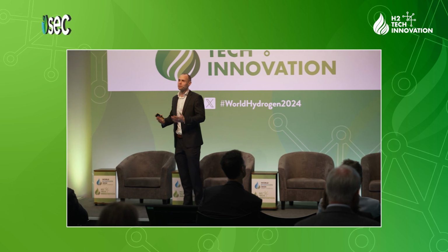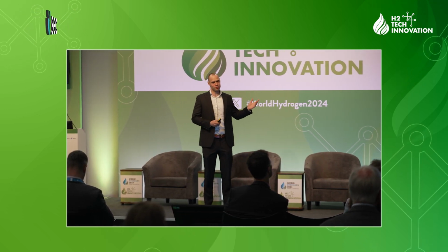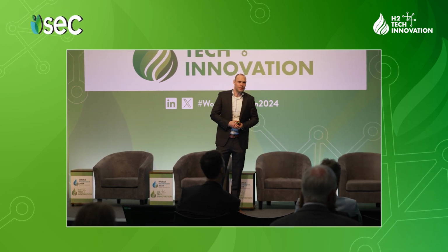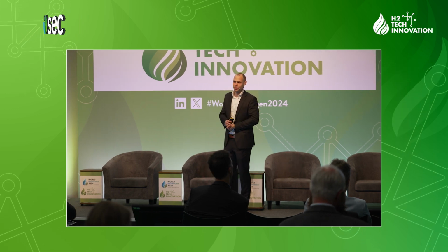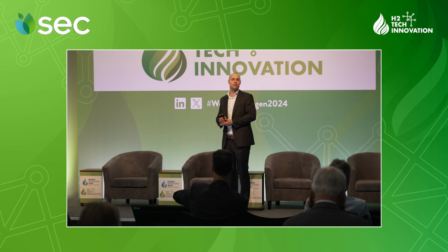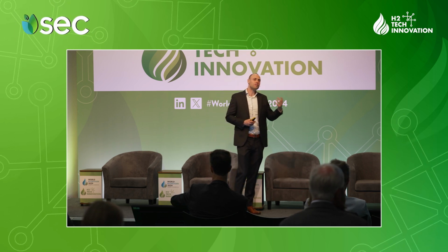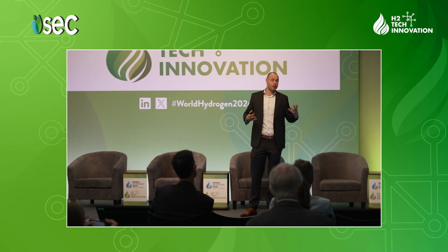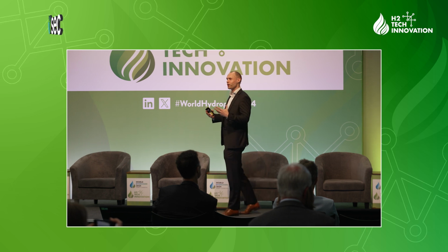Now, in terms of hydrogen production, I've listed a couple of sample examples here. For example, steam methane reforming is still being used a lot, and the process is not without issues. So catalyst poisoning and deposition of carbon are issues that are being investigated. And simulation can then tell you that, and it can also give you insight into the gas flow, reaction rates, and temperature, and this allows you to optimize the design.